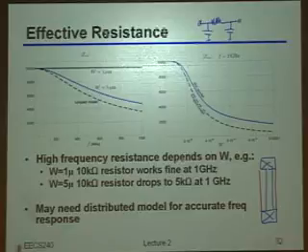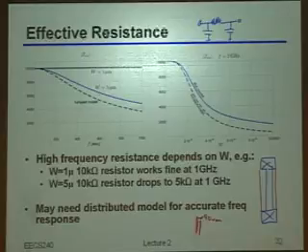Okay, so to give a somewhat exaggerated example, let's say you're really aggressive. You say, you know what, I'm going to take my gate poly, which in our process we said was like 90 nanometers, and I'm going to use that for all of my resistors. And let's say that in this particular thing you're trying to do, you have to push 2 milliamps through that poly. What's that poly going to look like after, I don't know, an hour, 2 hours, maybe 5 minutes, something like that? What poly? Yeah, what poly? Okay, that's actually the best answer I heard. I heard melted, I heard electromigration. What poly, right? The thing is just going to explode. There won't be any poly left there.